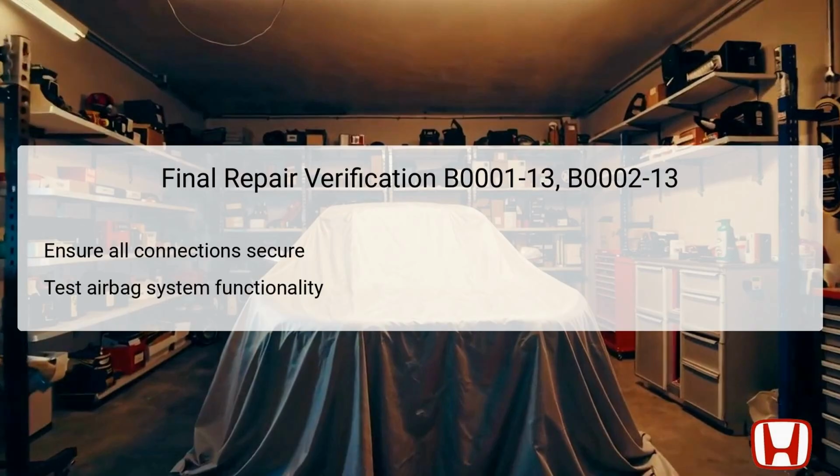Following this verification, a practical test of the airbag system functionality is recommended to ascertain its operational readiness before handing the vehicle back to the customer. Any saved DTCs should be reviewed to ascertain they were successfully cleared. If issues persist, full reevaluation of the wiring and SRS components may be necessary. Performing this thorough final check is key to ensuring the utmost safety during vehicle operation.